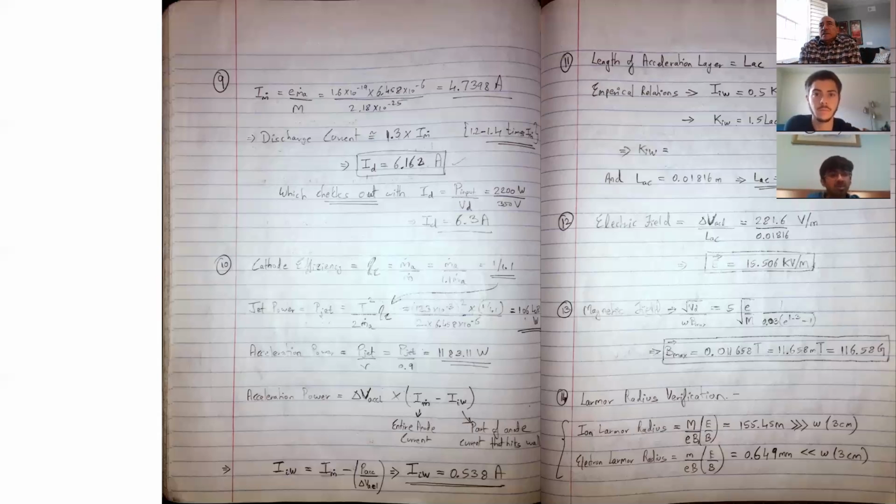That's the way to think about it. Let's say the ions are coming out of the Hall thruster; there are two possibilities. Either those ions recombine with the electrons from the cathode to give the whole atom, because it needs to be neutrals which are sent out. Only then the body itself doesn't get a charge, which is why you have the neutralizer cathode. So one possibility is it goes out as neutrals, or the other possibility is this ion also somehow goes into the cathode. A very small portion can possibly go into the cathode.